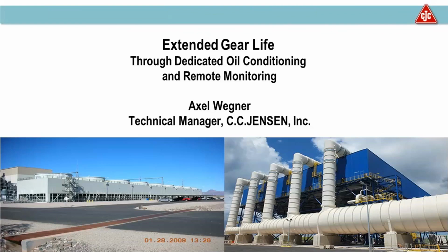And for your case specifically, I would just get one unit for one of your gears and install it and let it run, and show your practical, real-life results to justify that. We can guarantee that the cleanliness levels are going to be 16, 14, 11 or better if that filter runs.